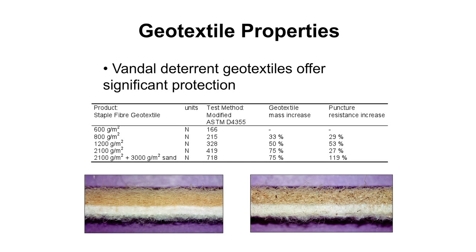Where the big jump comes in is when you add the sand into that layer there. That sand layer is effectively your protection to the geotextile. And what you're getting is a material that naturally accretes in the geotextiles themselves. So this is not something that you're having to add in the factory and add cost to your material. It's just something, when you finish building your structure, we'd recommend that you dump a load of sand on the top of it just to get that sand into the containers.